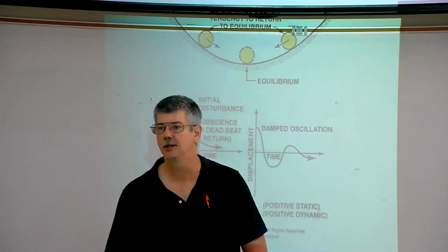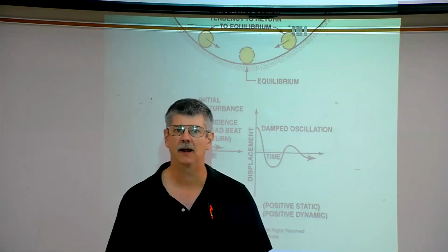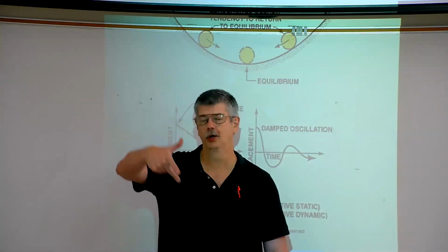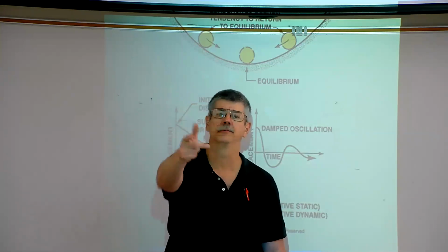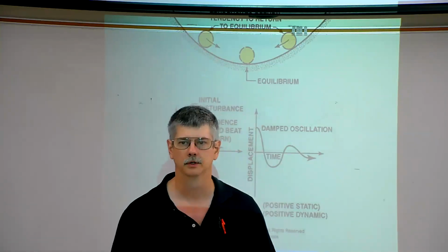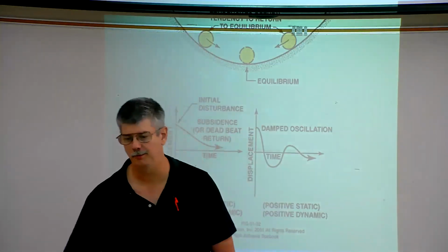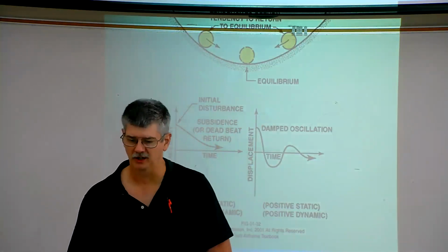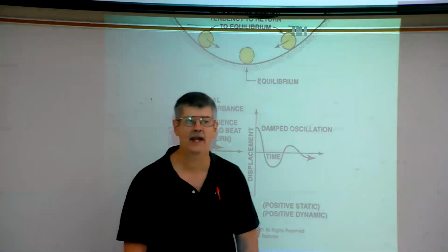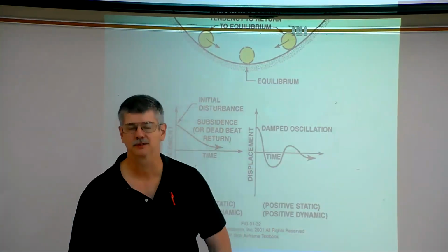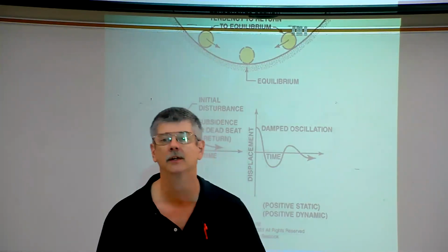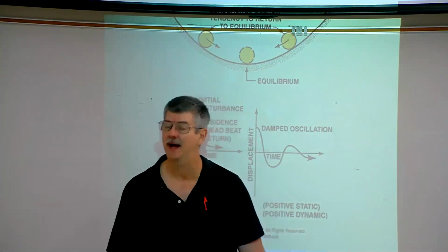And what that would do is that the aircraft, if it is upset by outside forces, will regain and fly at the attitude that the pilot has trimmed the aircraft to be. All right, not going to go heavy more than that. Oh, except for this one. If the aircraft has a positive dynamic stability, what type of static stability must it also have? And the answer is positive.